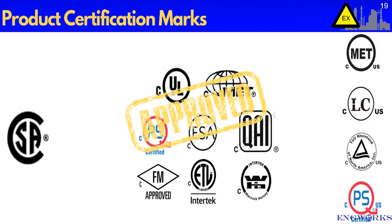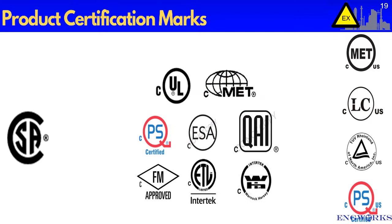All electrical products intended to be installed using the Canadian Electrical Code must be approved. A product is approved if it has been certified by an accredited certification or inspection body that it meets the safety requirements of a recognized Canadian product standard.